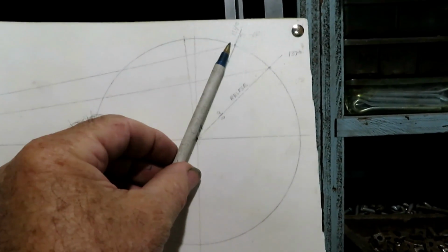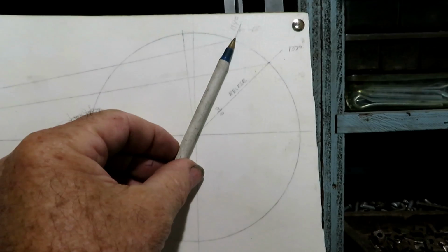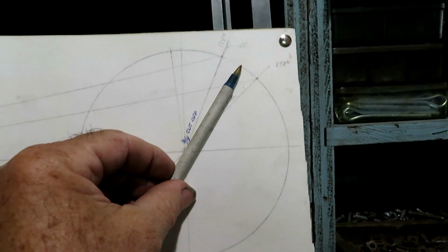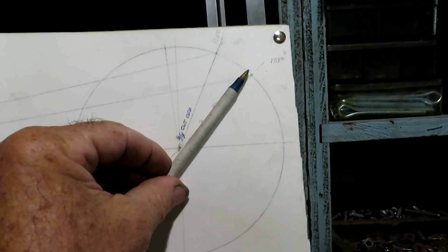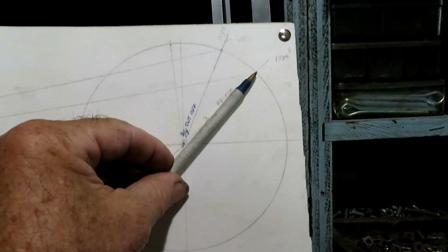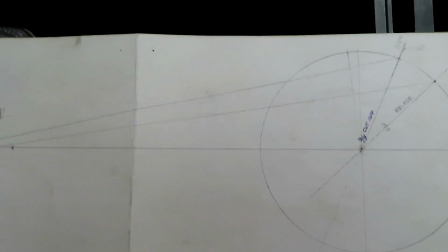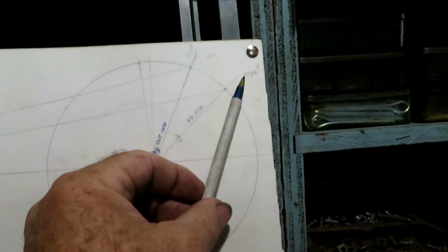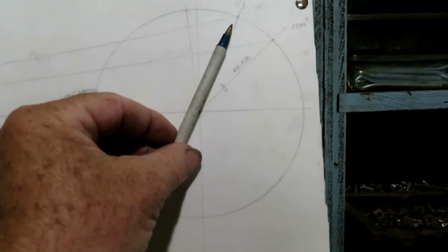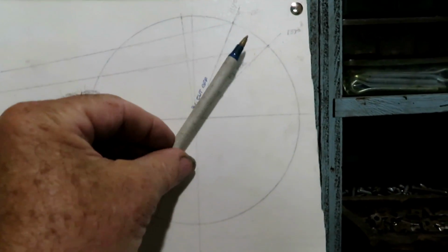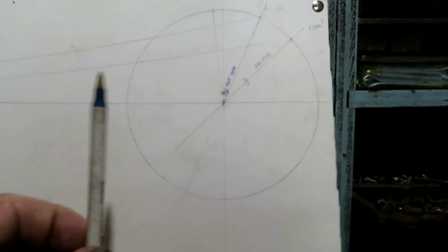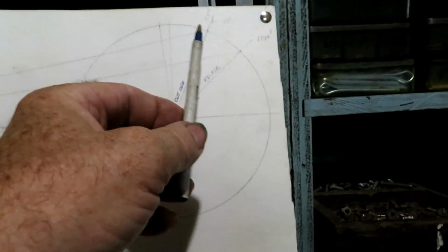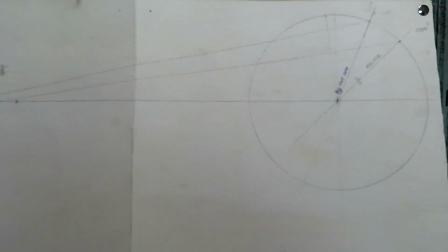And then after the steam is cut off, it continues to expand till you get to right about here, and 9/10 of the stroke, I calculated with a 15-inch rod to be 137 degrees. So this is the cutoff line, this is the release line. I measured these angles, 114 and 137, and transferred them to a Bilgram diagram.